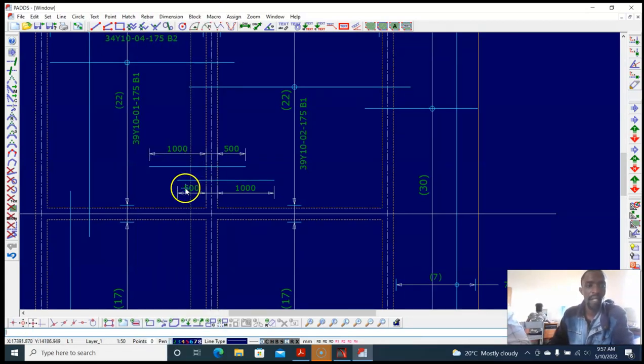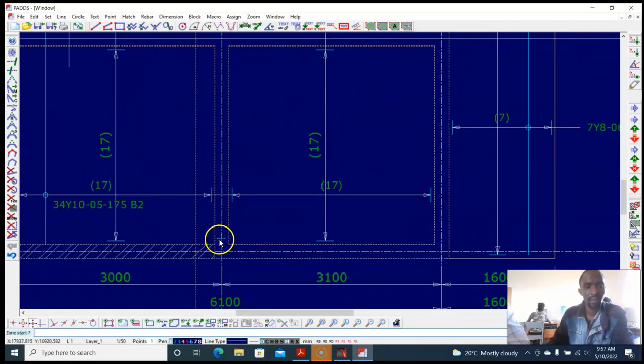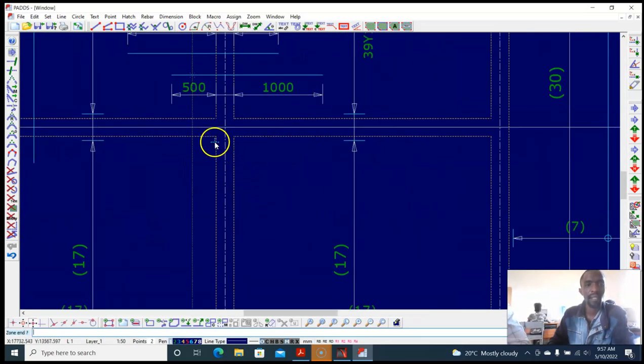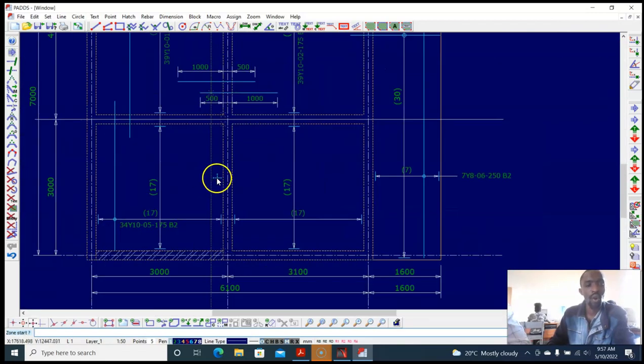R5. I mean, pick this rebar, R5. Start there, and end there. So what spacing do we get? 200. And we got 200, so in the middle it is 100 where they meet. So we're going to space these ones at 100. We space at 100.